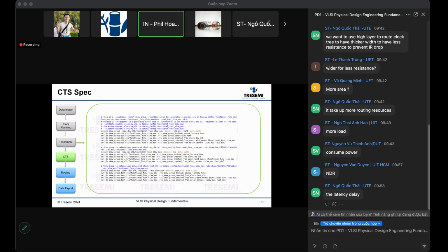If they're not excessive, then you just go with that. The problem with defining the target latency is that you don't know what will be optimum. So it's just something you need to understand, the relationships and also the impact of different constraints here, so that you can make the right decision in constraining the clock trees.